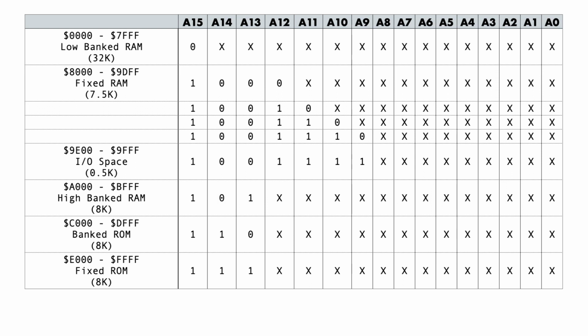Third, the banked RAM regions should be flexible. So, for example, a program might have a small code size that could fit into 8 kilobytes of RAM, but maybe it operates on a large data set that can benefit from having large bankable regions available. Alternatively, a program might have a relatively large code footprint, perhaps even in excess of 64 kilobytes, but operate on a comparatively small data set. Maybe something like a handful of state variables in a command buffer, or game levels or something like that.